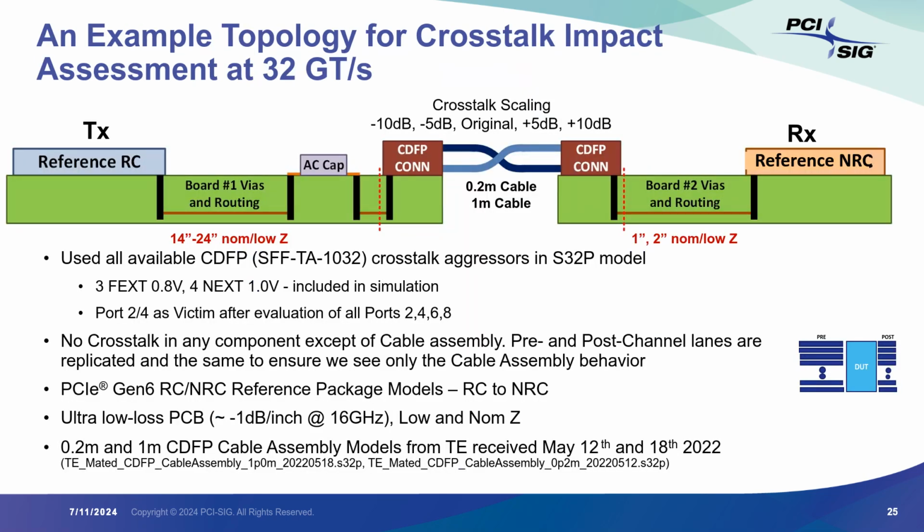Similarly for crosstalk, we look at how the crosstalk of the cable alone impacts. So we create models where we basically turn off the crosstalk of all other components. And then we vary the crosstalk, like near-end crosstalk and far-end crosstalk, and then look at how the crosstalk of the cable alone is impacting the performance, because we do not want the cable reflection or crosstalk to become a limiter for the end applications that we are looking for.